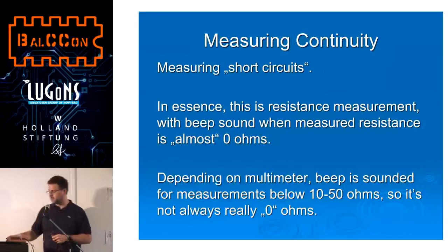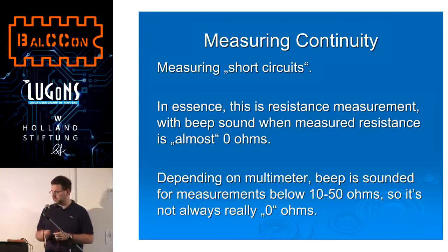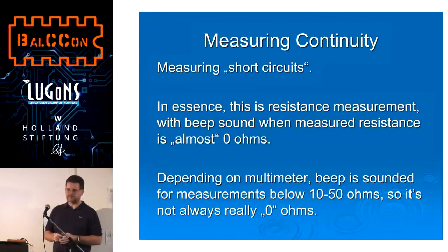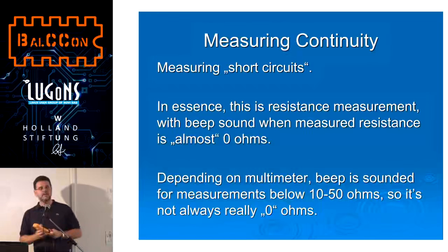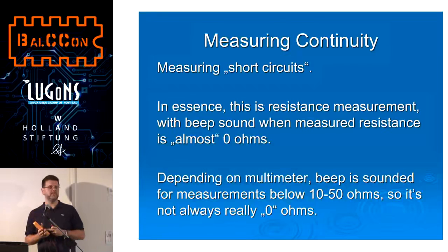Continuity. Well, that's popular with some people, and it does this. Actually, this is resistance measuring, and it checks if the resistance is less than 50 or 20 ohms, and that's considered a short circuit.